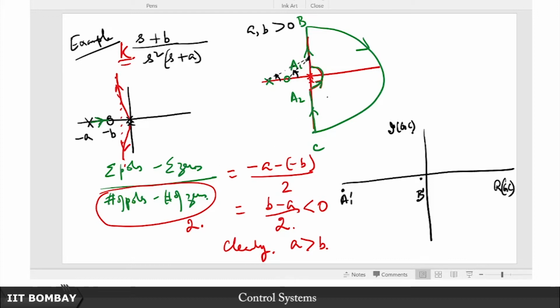So first you had a clockwise rotation of 180 degrees due to these pair of poles at this point, yeah, and these two, the other two remaining pole and 0, the non-zero pole and 0, yeah, that is A and B. So this is minus B, this is minus A. So this minus A and minus B, yeah, they contributed some additional positive phase to it. So that forced your plot. So I am not again bothered about the exact shape of how this came about, but it could very well be something like this. I really do not care about the exact shape.